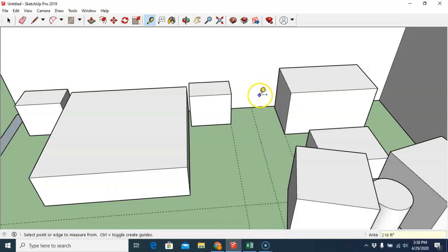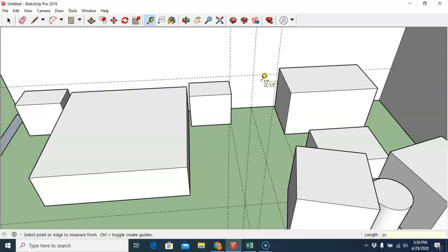And so now what I'm wanting to do is put a line on this wall. I want a vertical line at this point. So my window is 3 feet, so I'm going to go over 18 inches. And then I'm going to go over 18 inches in the opposite direction. These are in the red direction. It is 30, let's take it 30 inches off the floor.